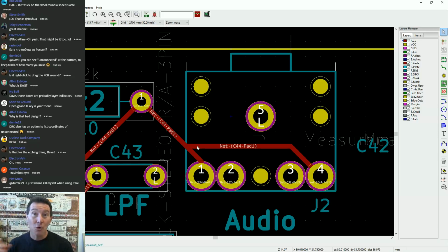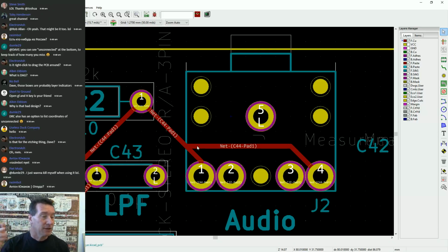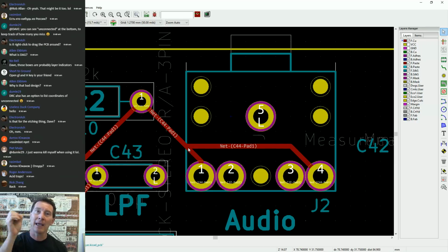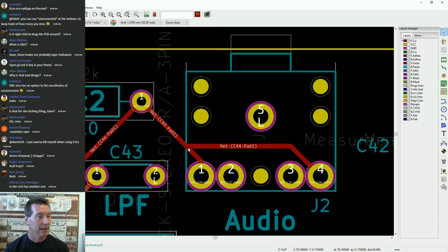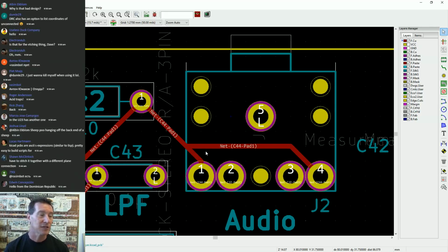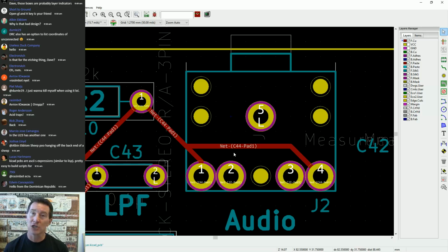Anyway, it's all agitating in there, so when you've got sharp angles like that, the etchant can build up in there and etch more away. So in theory, you could actually get over etching in that particular space. That's why you don't want sharp angles like that.